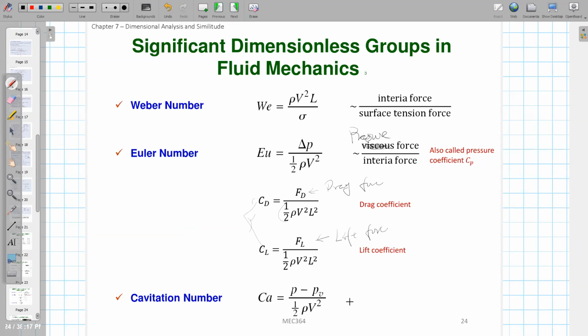So if you reduce the outside pressure so that it is even smaller than the vapor pressure of the liquid, the vaporization behavior will happen. Some liquid particles will escape and become gas. In that case, you will form small cavities, because the gas inside the liquid will create small bubbles.